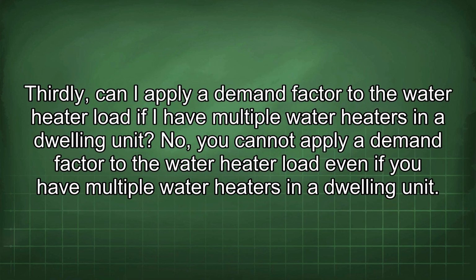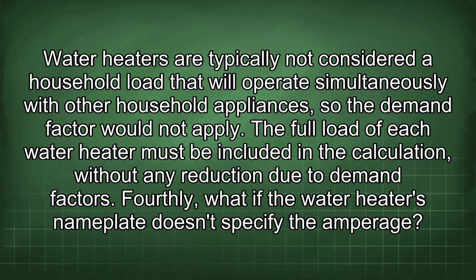Thirdly, can I apply a demand factor to the water heater load if I have multiple water heaters in a dwelling unit? No, you cannot apply a demand factor to the water heater load even if you have multiple water heaters in a dwelling unit. Water heaters are typically not considered a household load that will operate simultaneously with other household appliances, so the demand factor would not apply. The full load of each water heater must be included in the calculation, without any reduction due to demand factors. Fourthly, what if the water heater's nameplate doesn't specify the amperage?